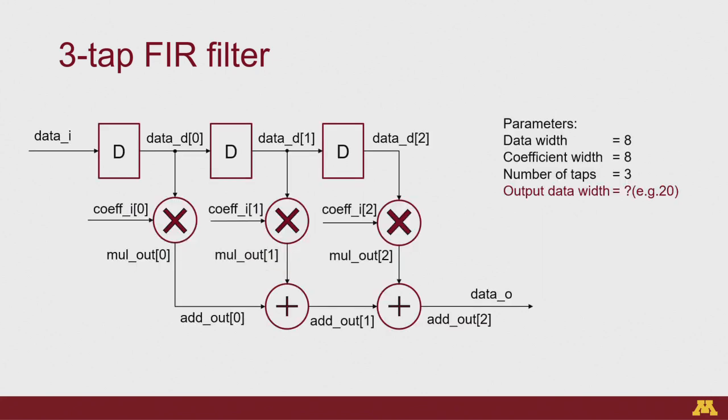Not related to Verilog, but there will be a minimum output width, right? Around 16. Yes, that's right. If you multiply 2 8-bit numbers, you will get 16 bits. But as a designer, you have complete control. If you want the final result to be again 8 bits, you can do that, but then you need to add some logic to actually handle that.